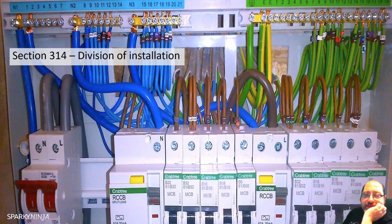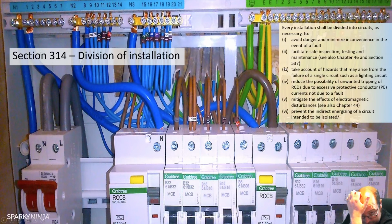Now with these, quite often you get questions on them. Avoid danger and minimize inconvenience in the event of a fault. This could be where you have a fault occur and then you have a power loss, which can create further danger. To facilitate safe inspection, imagine that you were in this installation and you had no way of isolating just this circuit. You would then be encouraged to work live because you wouldn't want to isolate this and turn off all of this.